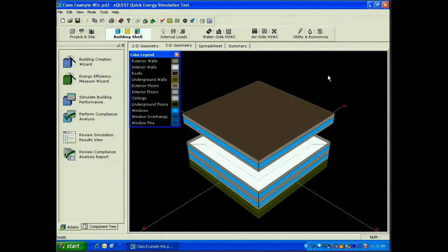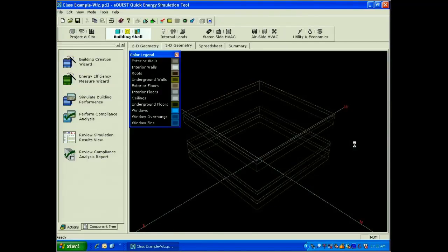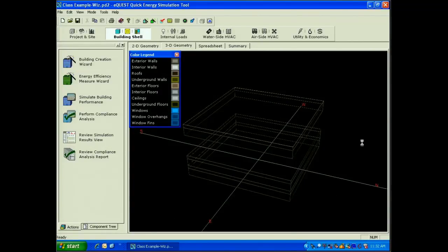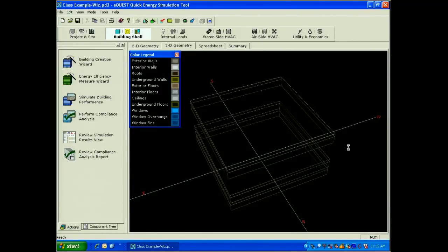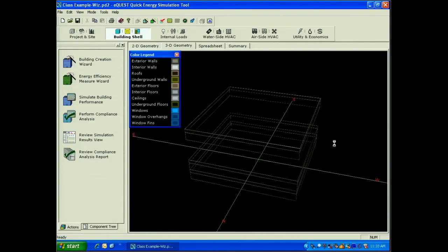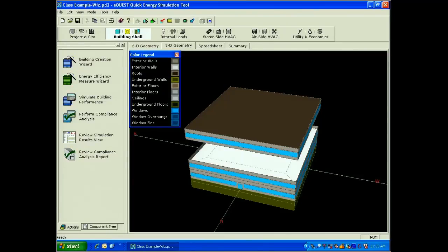Within this 3D view, we can look around by holding down your Control key and then pushing down on your left mouse button. While you're holding it down, you see that it's now a wire view instead of a solid view. It's just faster for the graphics program to draw it within a wire view. Then release the left mouse button, and it stops at that view.